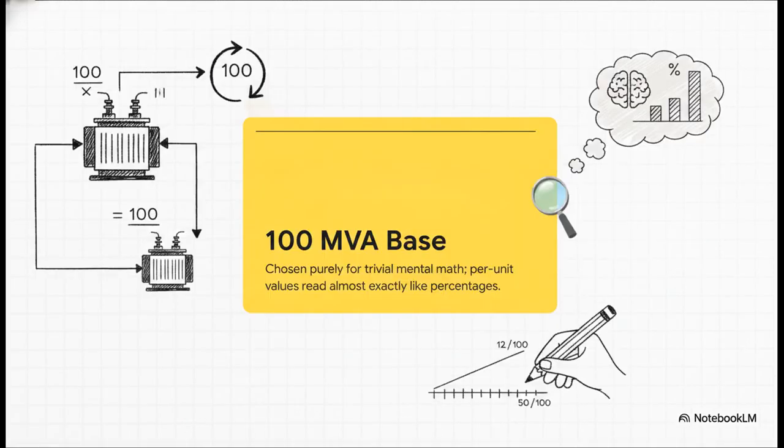Well, let's demystify the standard. There is absolutely zero physical reason for it. None. It was chosen purely for trivial mental math. Think about it. Dividing or multiplying by 100 is instant. It allows all those per unit values to read almost exactly like percentages. So a 12 MVA transformer? It instantly reads as 0.12 per unit of system capacity at a single glance. That sheer, simple, human convenience is literally the entire reason 100 MVA became the undisputed industry default.